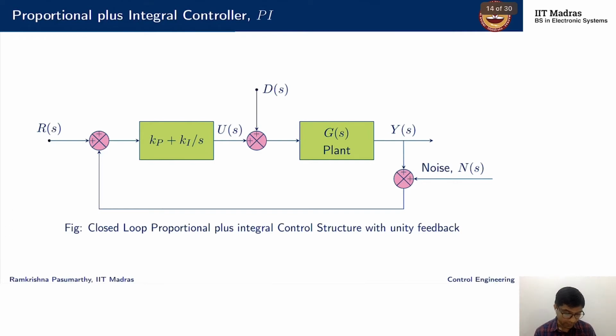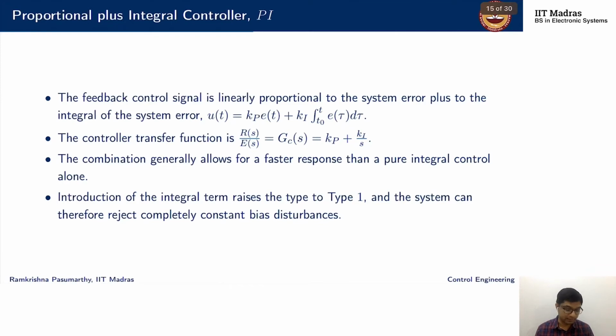Okay, we now look at what we call proportional plus integral control. Derivative control by itself kind of means nothing, and integral control by itself may have a few drawbacks. So we'll see what happens when I add a proportional term to the integral. I'm just looking at Kp plus Ki over s, and then I look at what happens in the steady state.